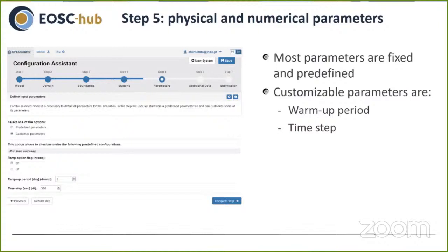If you aren't familiar with SCHISM, you may find this value to be too high. However, SCHISM is a semi-implicit model, and it's very stable. We therefore tend to use larger time steps than in other models.